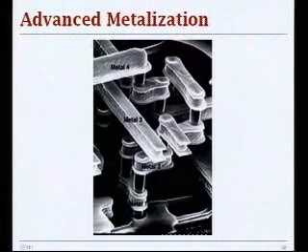So okay, now it's really interesting to see here, after you go through all these steps, you have this number of metalization layers on top of each other, and then you have these vias in between, which is a hole filled with metal that connects adjacent metal layers.